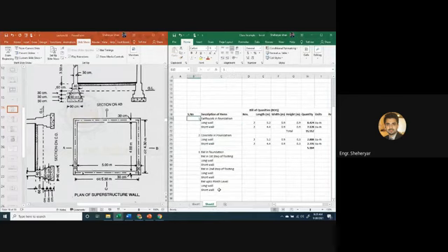Here I will make these bold so that we can identify which is the heading and which is the sub-heading. This one, this one, this one, this one, this one. Okay, fine. So now what will be the length of long wall for the first step of footing, which has a width of 60 centimeters? This will be 4.3 plus 0.6. Good.